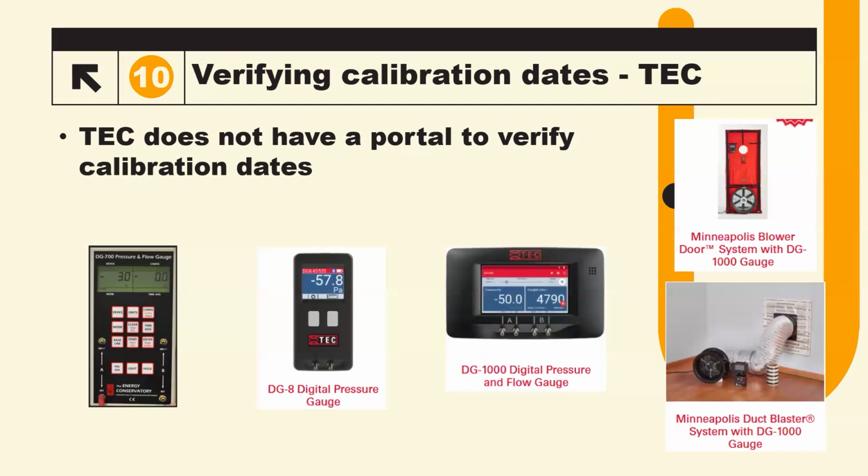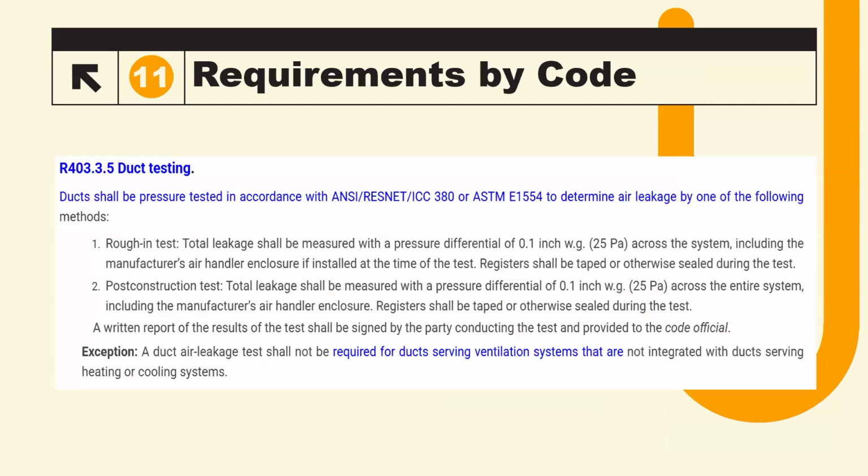a calibration log. If you're a HERS rater or a BPI or BSI, you're going to keep these logs and turn them in when you have your QAs done. They need to see those usually on an annual basis to make sure that you are indeed using equipment in the field that is kept up to date, has been field calibrated, and is also on a factory calibration schedule.